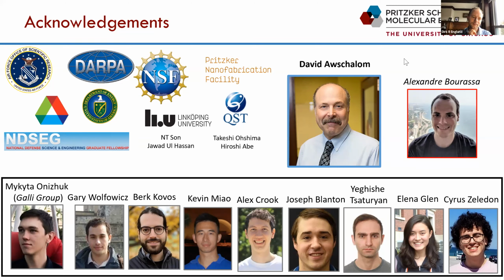But I also do think that there are some really exciting other ways to get thin film silicon carbide. People can create silicon carbide on an insulator, obviously. There are multiple ways you can think about it, right? And that's a smart cut or crystal ion slicing method. So the silicon carbide on an insulator is not smart cut. It's actually just wafer bonding and then a polishing. So they don't actually do the ion slicing. Yeah, and so people are thinking about combining these two methods as well to get some advantages.